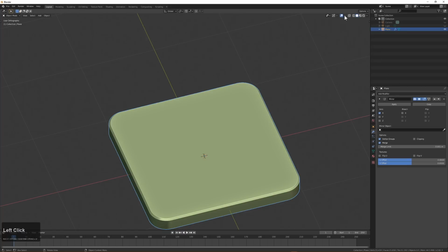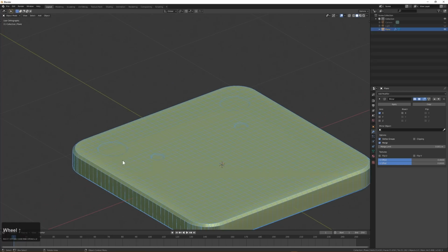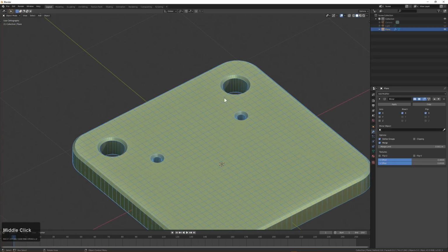And before we continue, let's turn on wireframe as well, because we want to see exactly what's going on. So we have it on X. We want to turn on bisect, and we want to turn on flip. And so now we're mirroring across here, but we're cutting it down the middle and merging that geometry on the level of the modifier. And because of that, this geometry is completely watertight and manifold. So it's prime for booleans, but also it's a good mesh.